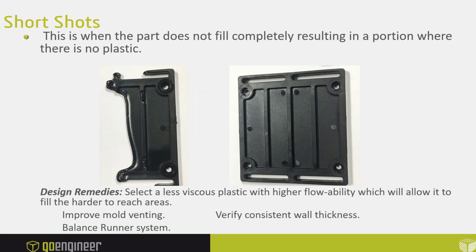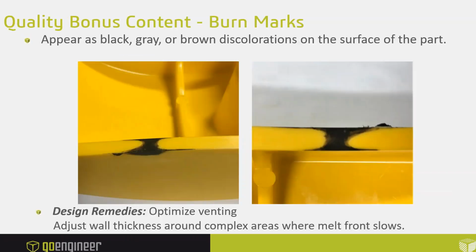How do you know if your part's going to fill, or how much pressure is it going to take, or what's the shot size, right? You can answer all these questions to make sure that we don't get short shots and waste material. Too thick or too thin, right? Some parts are just designed poorly, and no matter how hard you push the plastic in, it'll never fill all the way. That would be a bad mistake. That would be like a redo of the mold mistake, right? Reburn all the cavities.